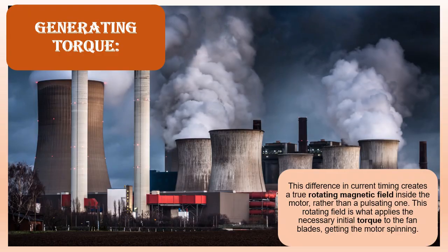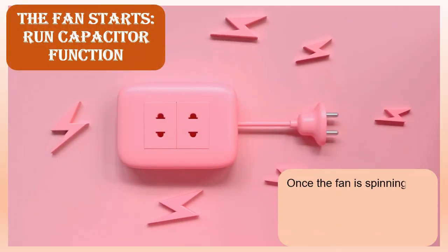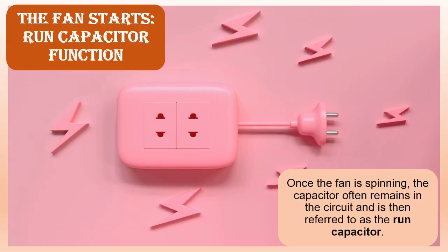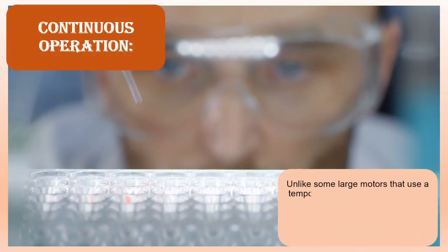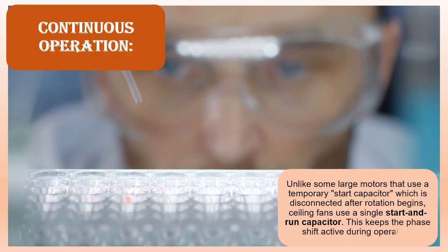Run capacitor function. Once the fan is spinning, the capacitor often remains in the circuit and is then referred to as the run capacitor. Continuous operation. Unlike some large motors that use a temporary start capacitor, which is disconnected after rotation begins, ceiling fans use a single start and run capacitor. This keeps the phase shift active during operation.